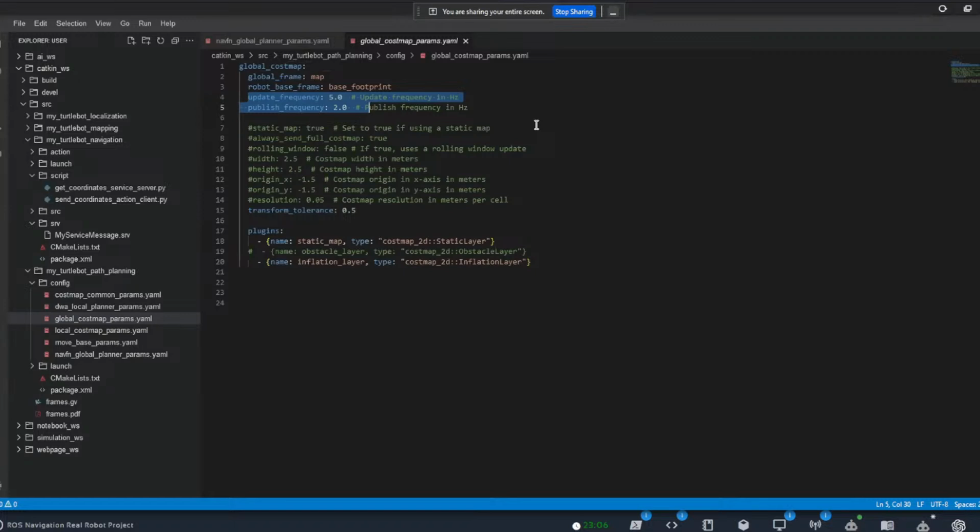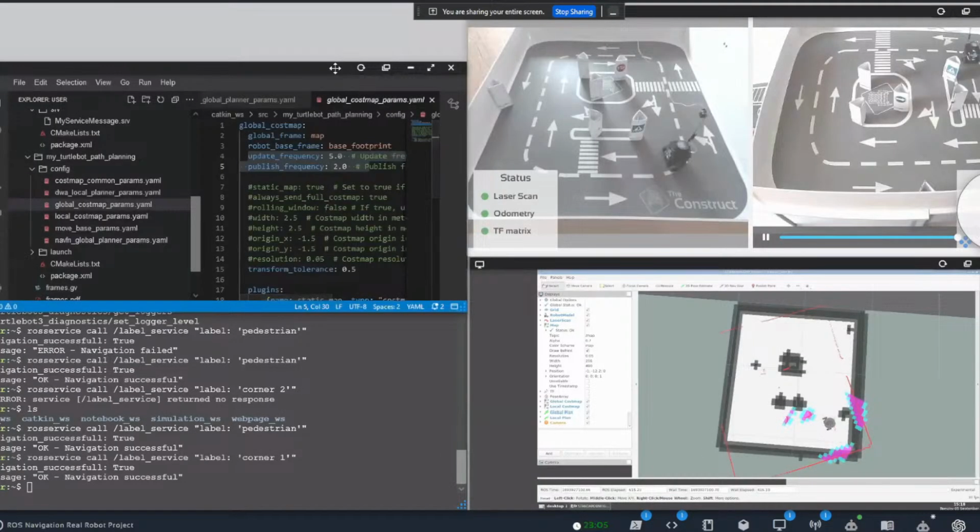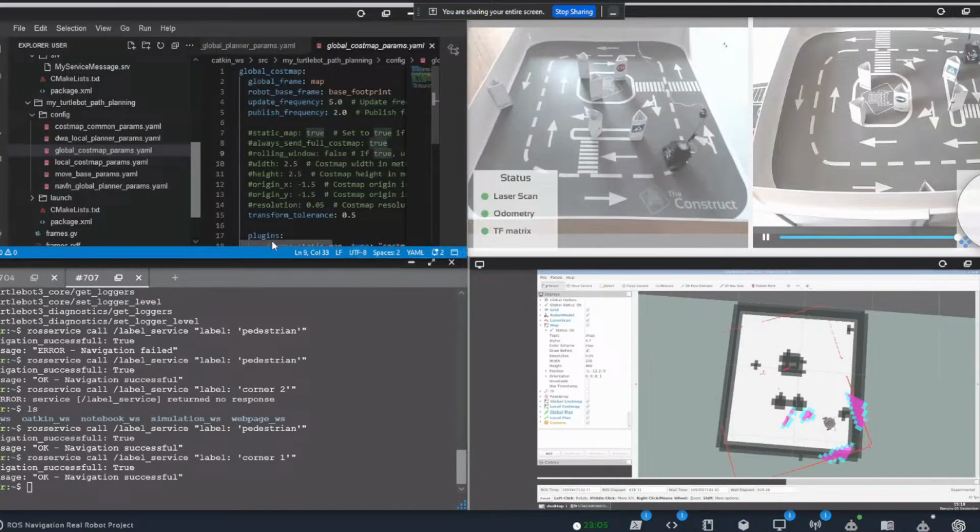I used these numbers for the update frequencies because in the real robot simulation, I was having trouble with higher frequencies. So it's a balance you have to strike. If you put it at 50 hertz or something, you're going to get a message that the loop didn't catch up in time because the controller is trying to go too fast to replan and everything.